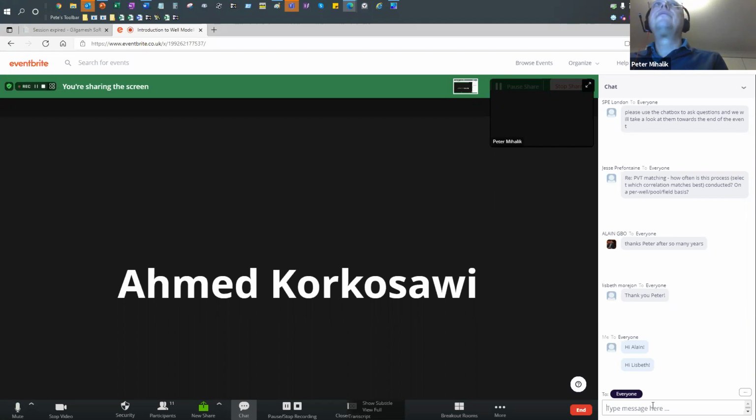Okay, thank you. I don't know if that answers your question particularly, but it kind of depends on how well you've described your wellbore, how accurately you might have tuned your well model to well test data. Have you chosen the right PVT correlation, for instance? Have you chosen the right flow correlation? All of these things can help if you optimize those. And then hopefully you get decent results at the end of it, but there's no reason to suggest that Prosper can't handle decent numbers for you.